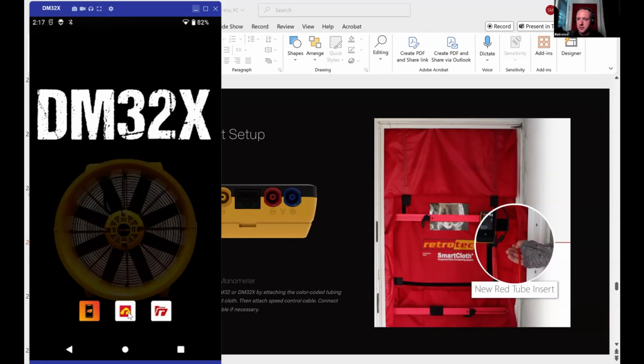We have our cloud, which I'll talk about in a little bit. And Joe Medosh, this was actually his brainchild when he was at Retrotec. And it's an automated testing and reporting app. If you get into blower door testing, I recommend you use this and run your tests in this. You can run some manual tests first to see where you are, but then use our cloud to report it. It'll save the test, save every bit of information about that test day, save the building information, and it'll tell you if you're testing the code, if it passed or failed.